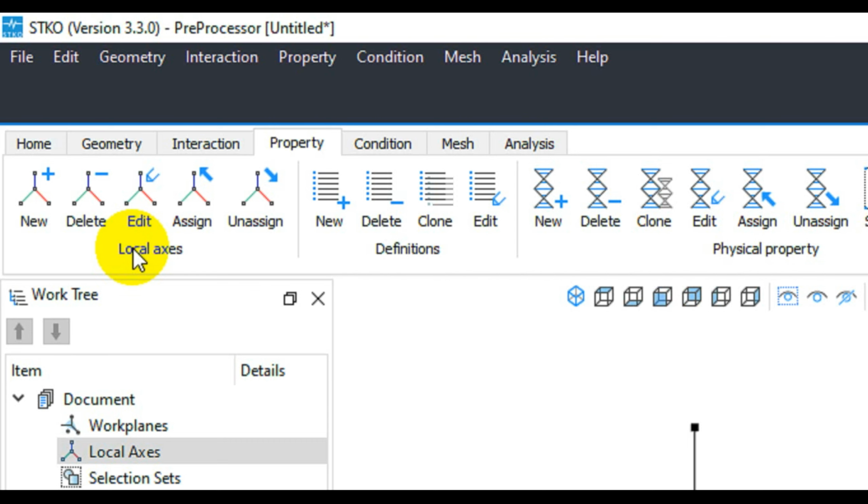Another thing is that sometimes we need accurate representation of loads and boundary conditions. The local axis determines the direction of the applied load. It also helps in the determination of constraints and other boundary conditions on the element. For example, for truss elements, aligning these correctly with the element orientation is very necessary for the analysis to accurately capture real-world behavior.